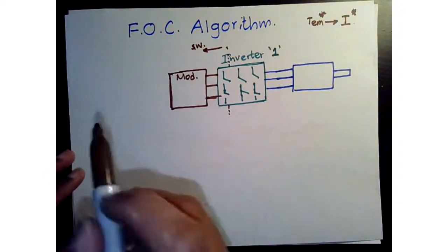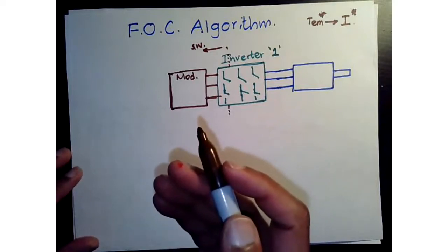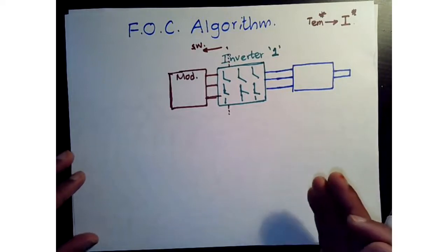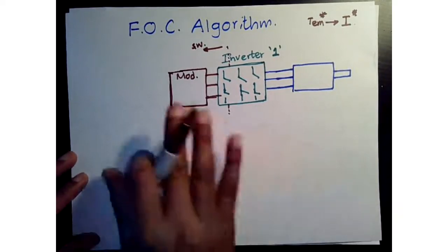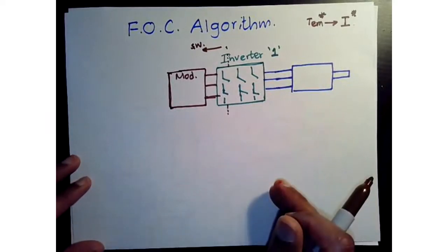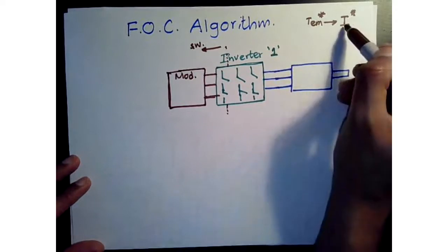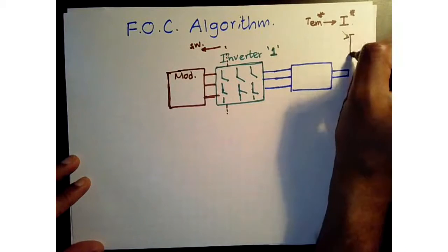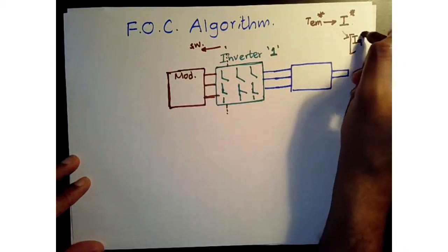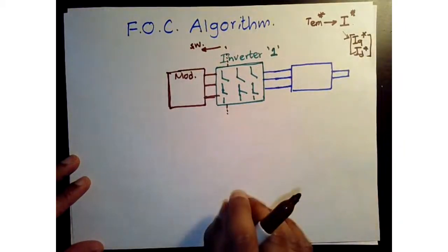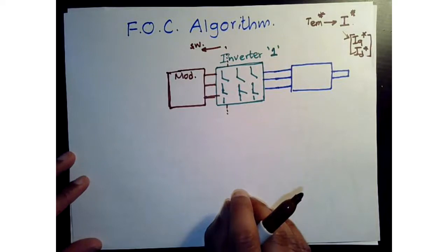Because in order to align our currents and voltages, either or, we need to know position. So why don't we use that position to our advantage and design our control system in this reference frame itself? Okay, so ultimately your electromagnetic torque is going to convert into an IQ command and an ID command. Just the two. Okay, IQ command and ID command.